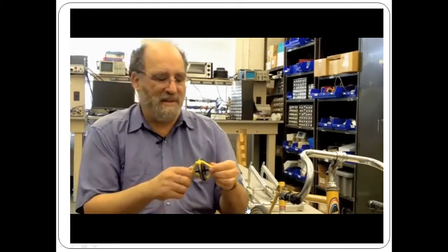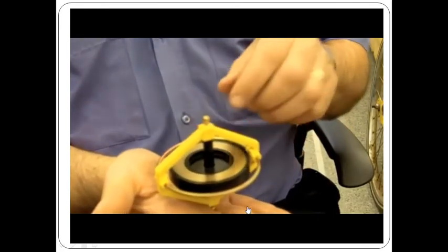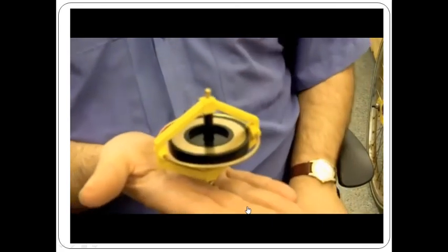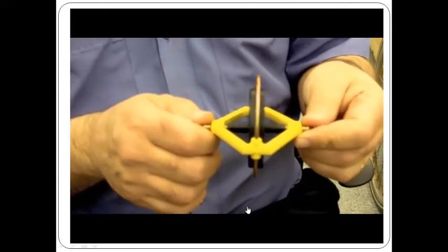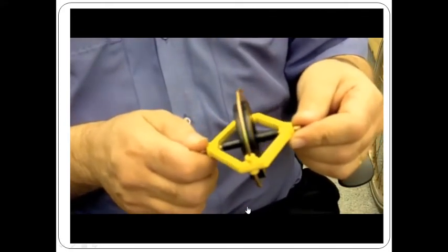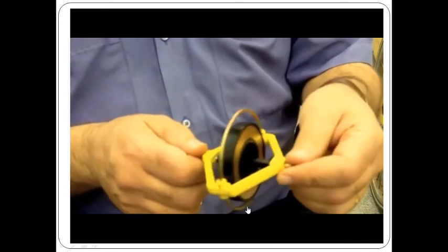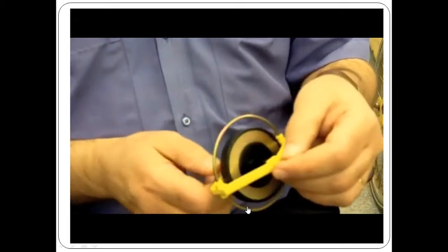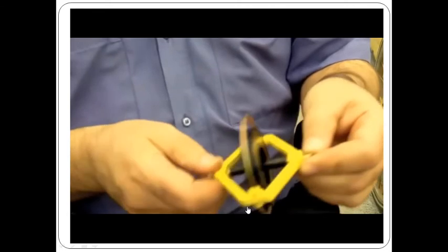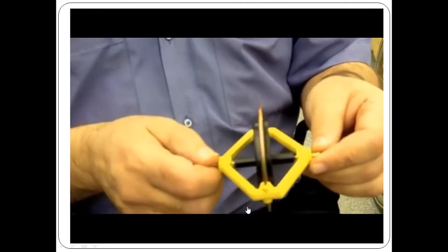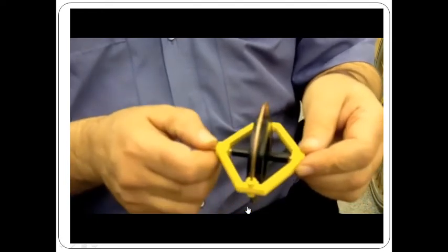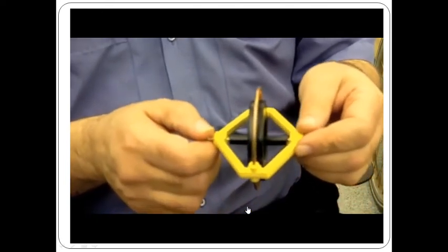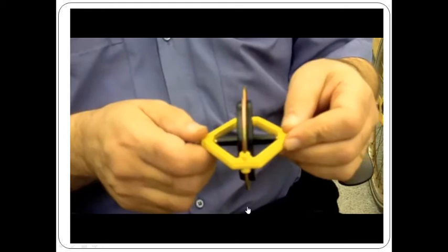And you would naturally think that a bicycle is stable because of the spinning. And as I said, what we showed is that when you tie the handlebars and don't let it steer, this gyroscopic effect doesn't give any stability. So what is it about the moving that gives it stability? This spinning gyroscope has this sort of squirrely aspect, which you can feel when you hold a gyroscope. It's not just that it wants to keep its alignment, it's that when you try to turn it one way, the effect is to turn a different direction.